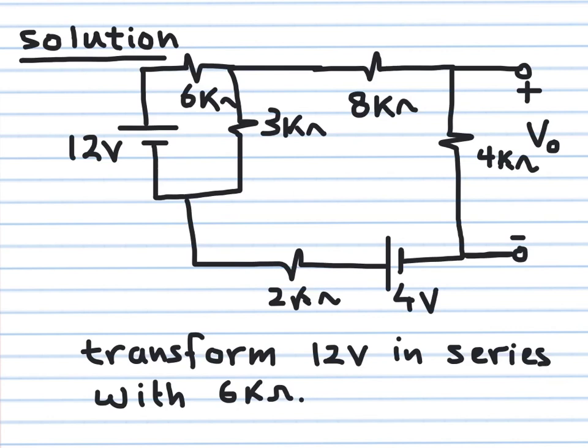So what I'm going to be doing here, I will try to open up the circuit. I will remove all these steps I have done, and we'll see how things look. So this is my target. Replace this voltage source and this resistance by a current source in parallel with the resistance, and then I will combine this new resistance with the 3 kilo ohm to get one equivalent resistance, and then convert that current source again to a voltage source.